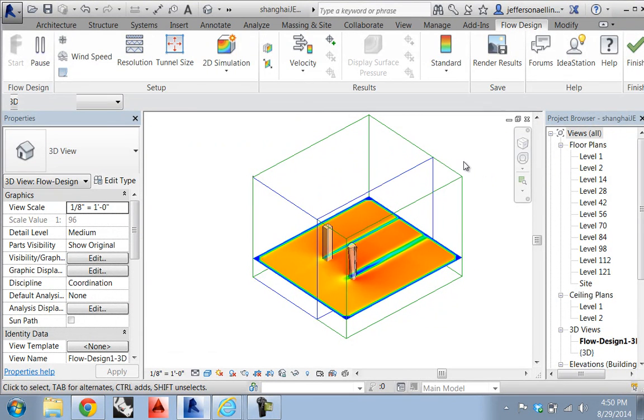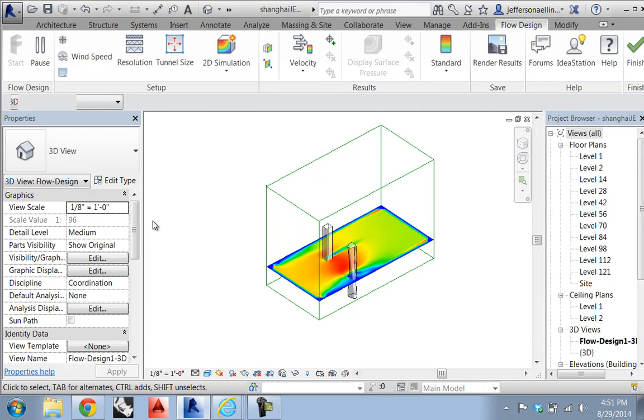with the bounding box. The smaller the bounding box, the less computation is required, because really what the CFD analysis needs to do is fill the volume of the box with air, essentially, and it does that by populating the box full of a three-dimensional array of pixels. But these pixels have information embedded in them, and so they actually call them voxels. Anyway, it's got to fill the entire volume so that it can understand how the air is bouncing off itself and off other things, which is why it's so computationally intense.